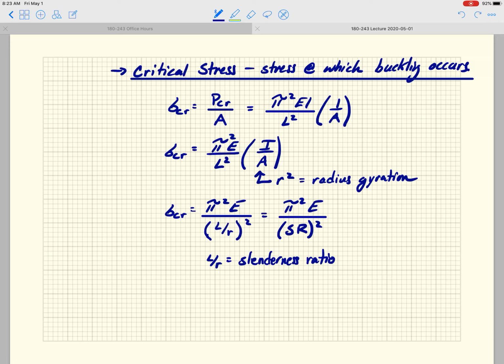And then you divide that by the radius of gyration, which is the moment of inertia divided by the cross-sectional area. In the steel manual, when you get to steel design next year, you will see that they actually tabulate these values R, so you can just go in there and pull it for any cross-section. In fact, I think they even tabulate the slenderness ratios for simply supported columns.